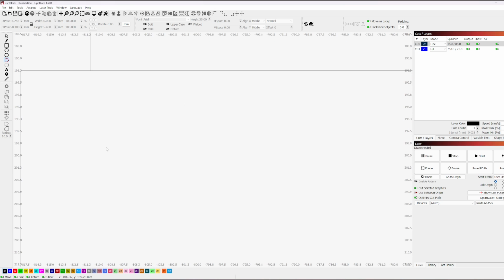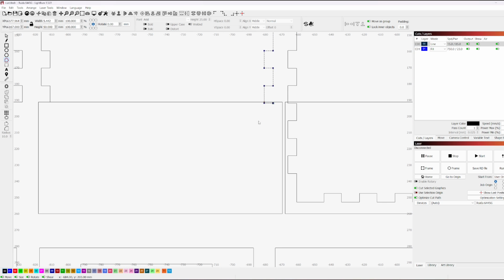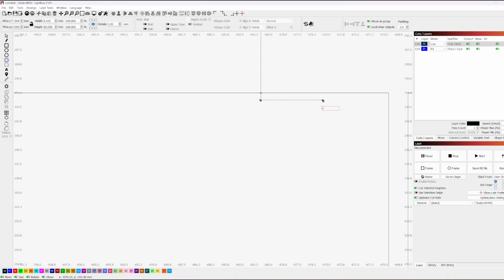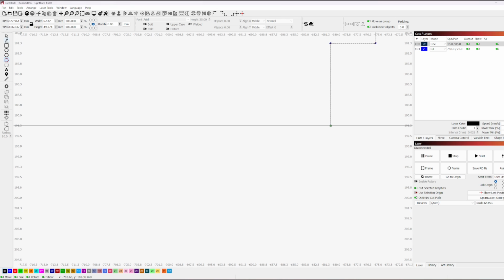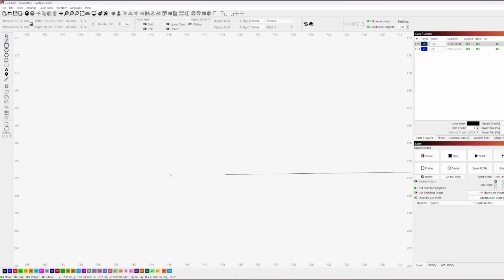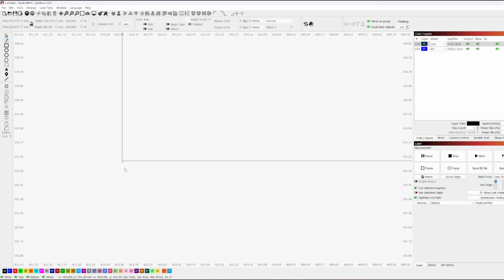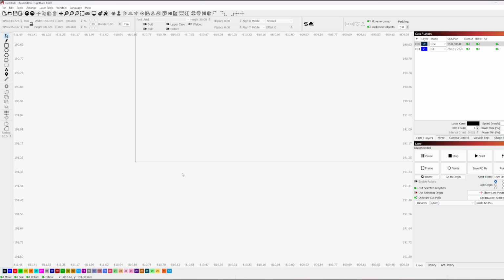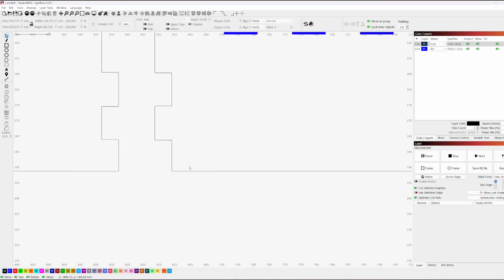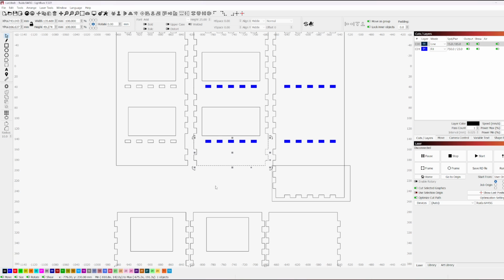Get rid of those. When you're modifying and you need to remove nodes, remember to use D instead of delete. All right. Now we can close this up. Remember to use those crosshairs because now you have a confirmed connected point. Now what I could do, you'll notice when I highlight this, it's just connected to parts of segments. I could go and correct this.